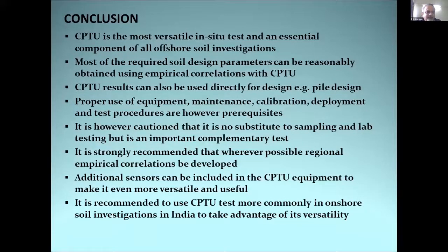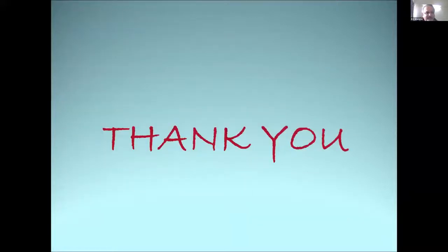Proper use of equipment, maintenance, calibration, etc. are prerequisite. It is, however, cautioned that it is no substitute for sampling and laboratory testing, but is an important complementary test. It is strongly recommended that wherever possible, regional correlations be developed. Additional sensors can also be included in the CPTU equipment for increased versatility, and it is recommended to use CPTU tests more commonly in onshore soil investigation in India to take advantage of its versatility. Thank you.